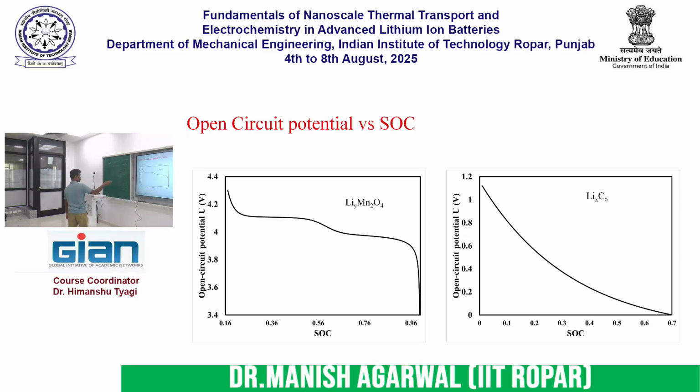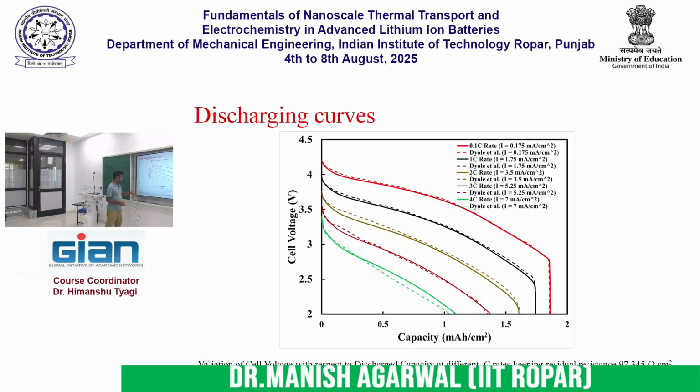Because the open circuit potential of the battery is the positive electrode's open circuit voltage minus the open circuit voltage of the negative one. So this is how it is varying with respect to the SOC. Again, based on the paper, you will see some variation in the result. So this is the final outcome of the simulation. Generally, this is the first thing that you report.